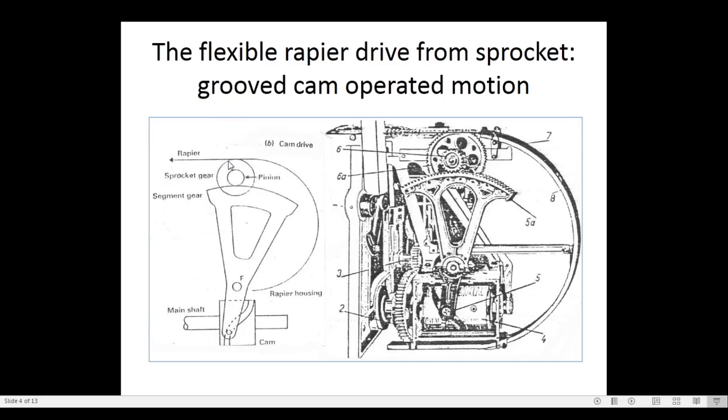So now the question is, how does this toothed sprocket move clockwise and anti-clockwise? So see here, when it moves clockwise, the Rapier goes in the housing, flexible tape, and when it moves anti-clockwise, Rapier goes up to the center of the machine. So like this, the drive system is present on the left hand side and right hand side. This is not connected to the sleigh, it is fixed to the machine frame.